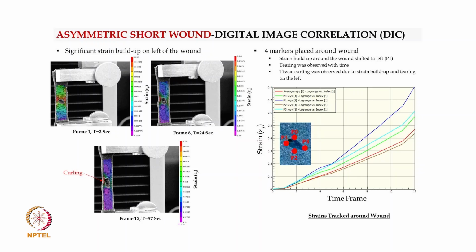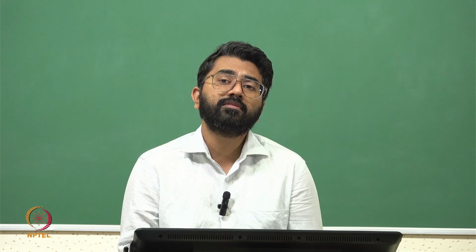Whenever you have this kind of condition, that local point is highly susceptible to a fracture or a rupture. So please remember, as a rule of thumb, whenever you have a very high strain zone surrounded by a low strain distribution, that is a place from which a fracture can initiate. This is a point of concern.